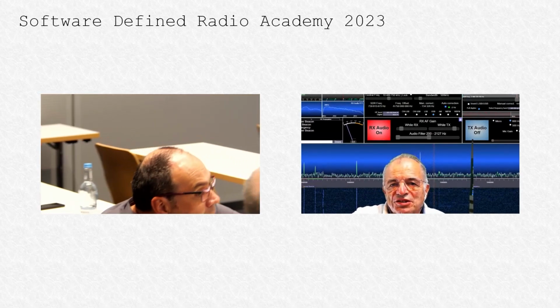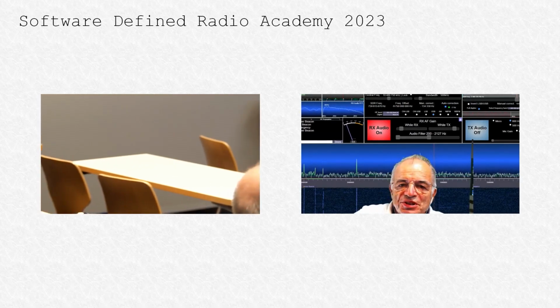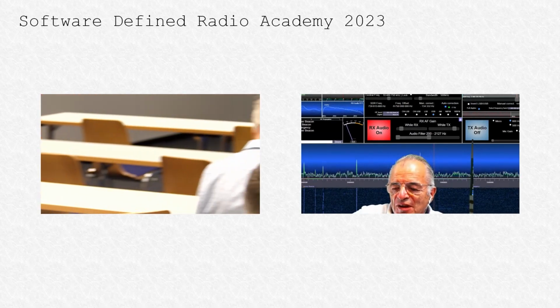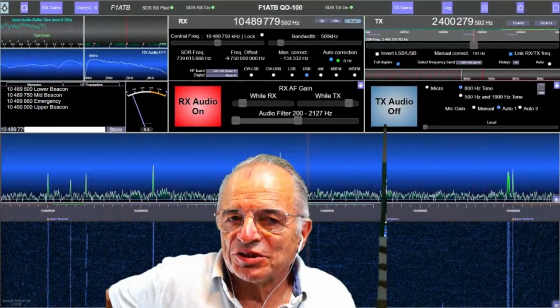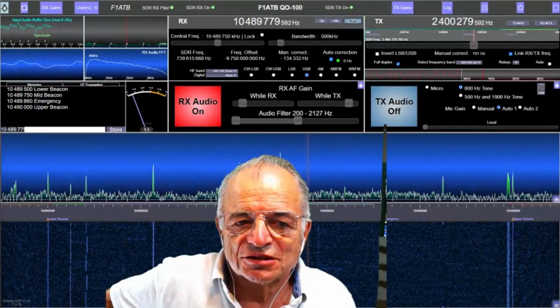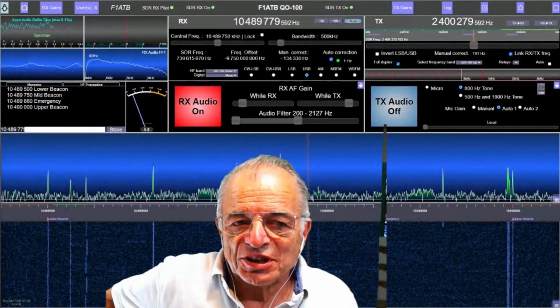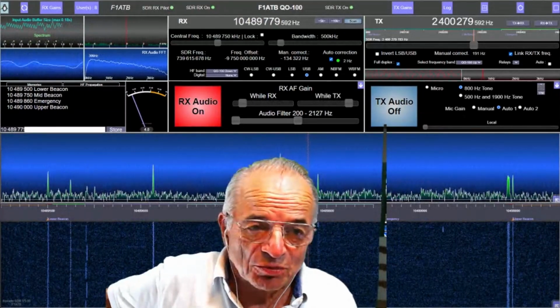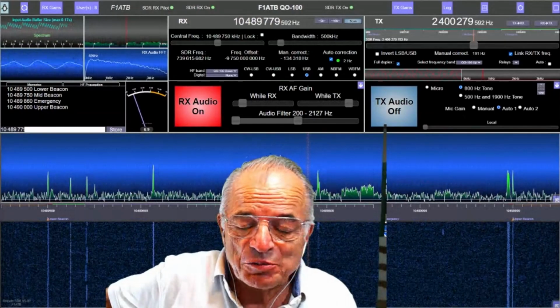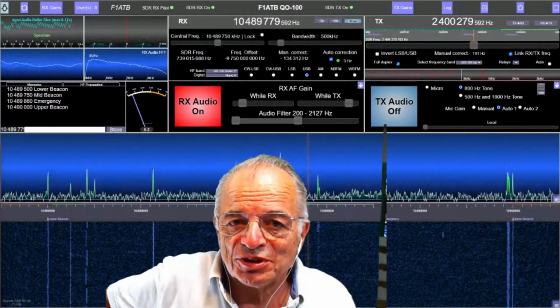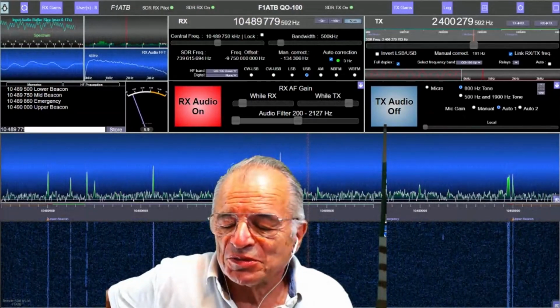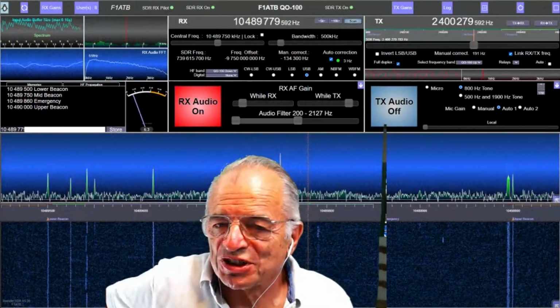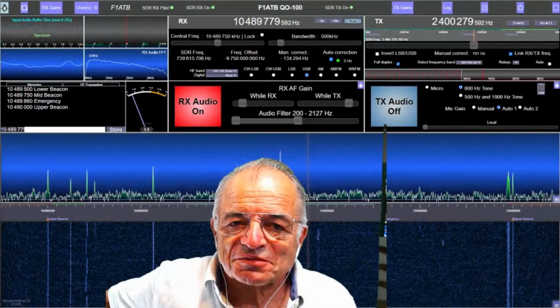No. Today, the system works only with a USB connection to the Pluto. And I have to say, it's often a difficulty because the data rate is quite high, and depending on the power supply you have for your Pluto and the quality of the cable between the Pluto and the Raspberry Pi, sometimes there are some difficulties, but they can be solved.